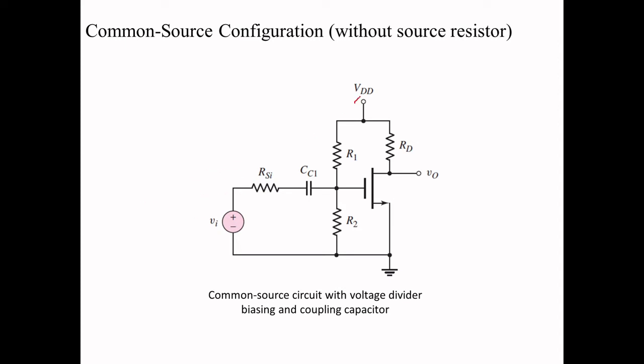First, what you want to do is remove the DC and short circuit the capacitor. That is the basic. Then you want to connect the passive elements to the ground. If you draw for this, what will you get? So you have a MOSFET. So first draw the MOSFET.